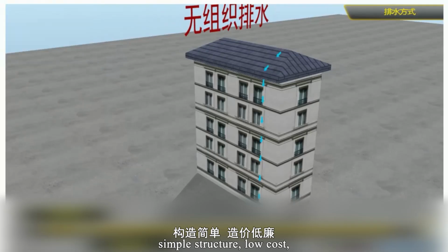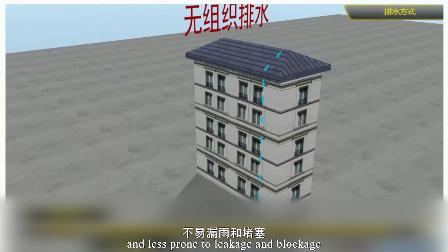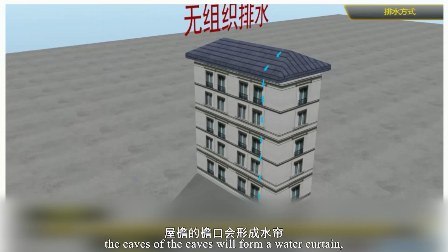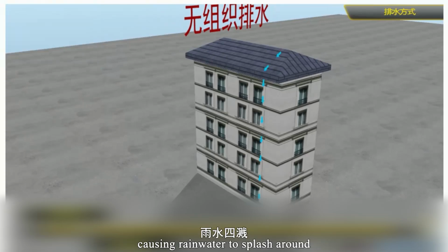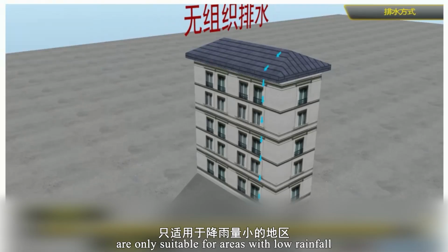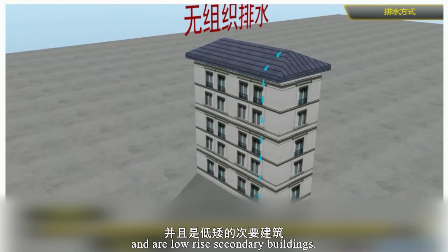Unorganized drainage has a simple structure, low cost, and is less prone to leakage and blockage. However, when the building height is high and there is heavy rainfall, the eaves will form a water curtain, causing rainwater to splash around and wet the walls, erode and pollute the walls, and affect the environment. Therefore, unorganized drainage is only suitable for areas with low rainfall and low-rise secondary buildings.